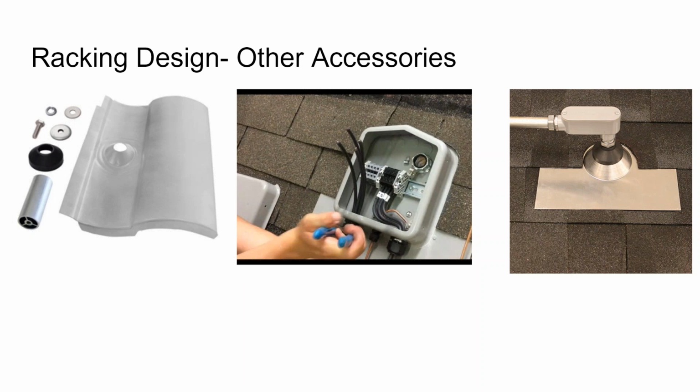Yeah, there's a question. Has hail damage, have you ever seen microfractures appear without any damage to the glass? The answer is yes. That's the scary part, is the microfractures absolutely can occur without damage to the glass. And if snail trails appear on your module, that's only one kind of microfracture. And again, that may or may not be the installer's fault. It could easily be the build quality of the module just as much as it could easily be the installer's fault. So at that point, it really comes down to who you used as the distributor for honoring the warranty.